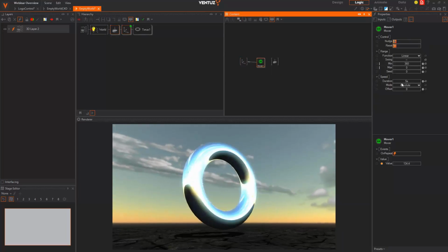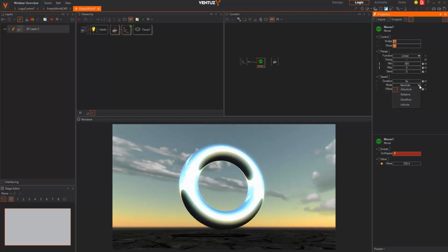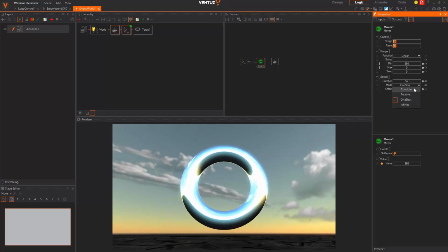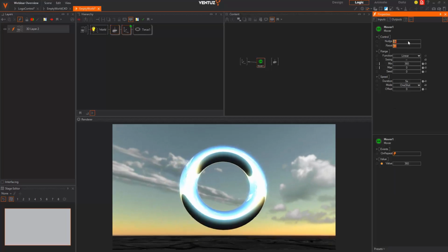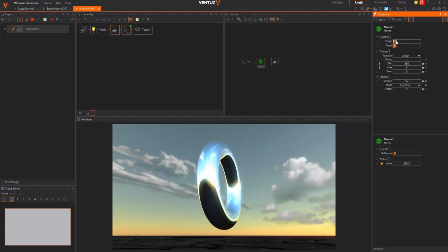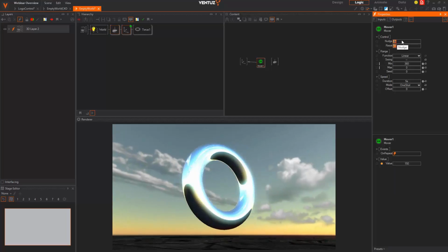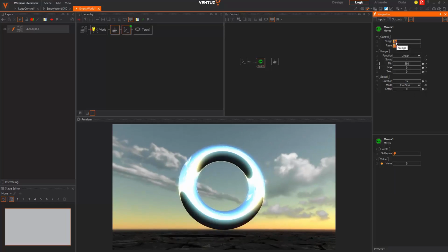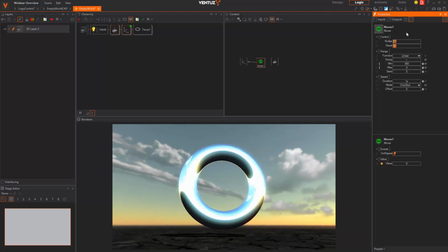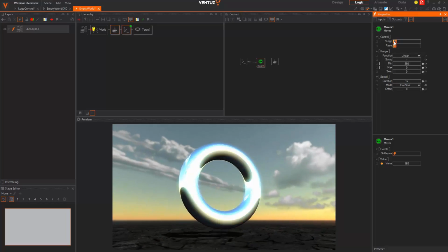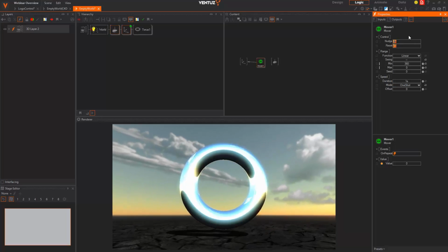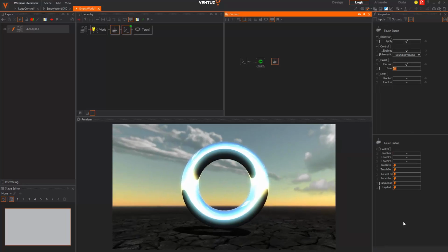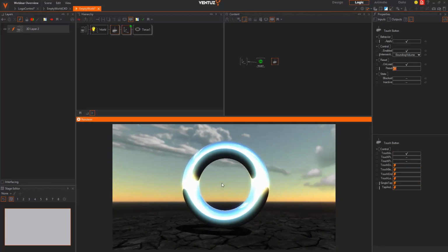And now we need to change the mode of the mover from absolute, which just rotates all the time, to one shot, which only rotates whenever we use the nudge method, which is also an input. So let's not make it 5 seconds again, but rather 1. And the method can be fired by any event that occurs on any other node. So for example, the touch button has events as outputs whenever we touch it.